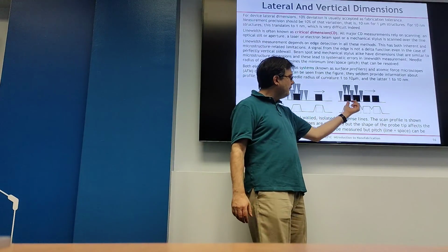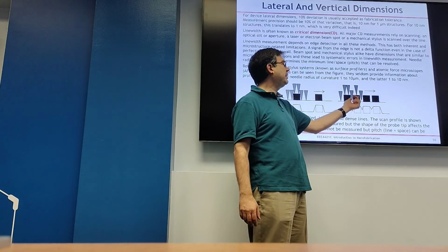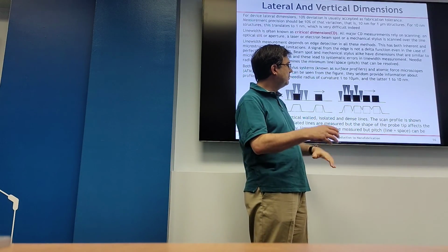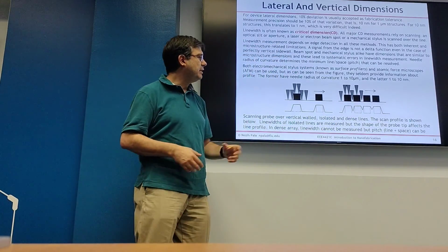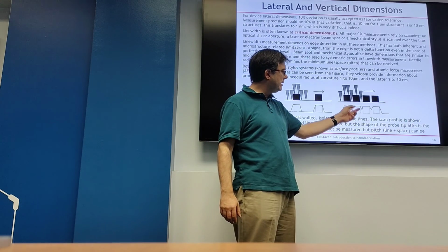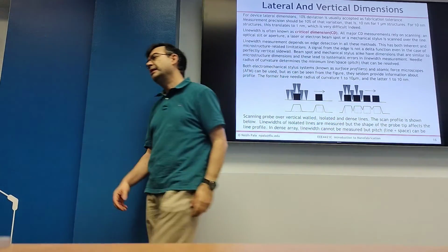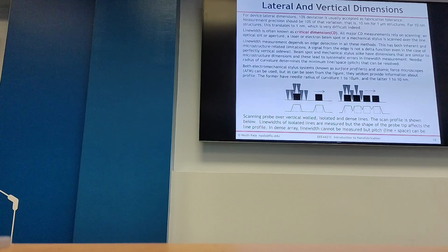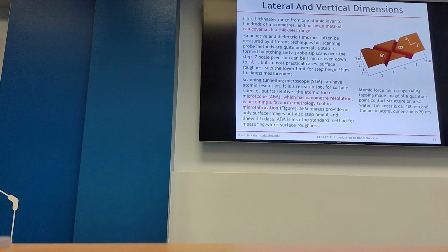But if they are very close, your tip may not go into the bottom of this narrow trench, and it may give you erroneous results. You may not accurately measure the height or even the separation. So you have to be careful about that. When you measure, is it within the limits or capabilities of your measurement tool? For this case, you may consider measurement using, I don't know, SEM or AFM maybe. Again, it depends on the depth and thickness for the separation.